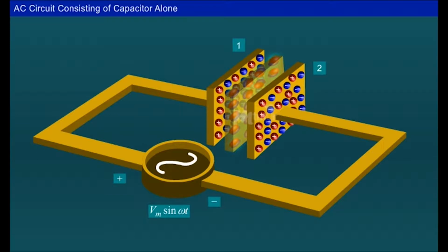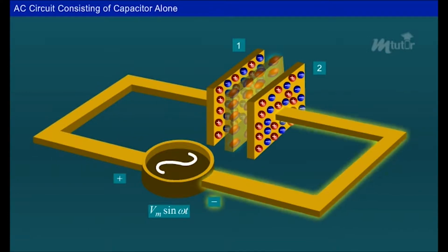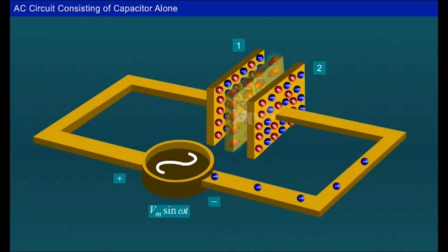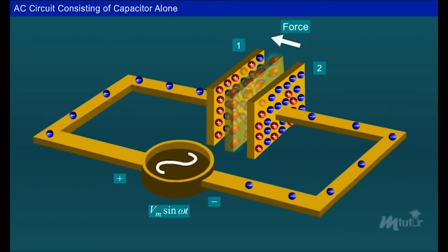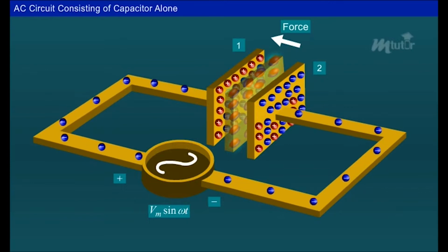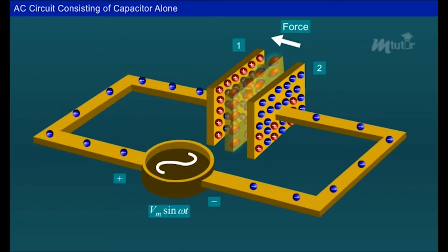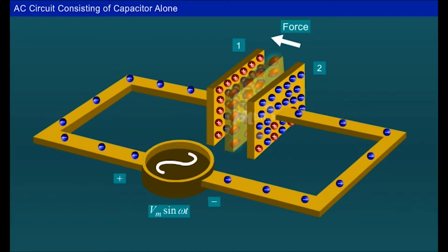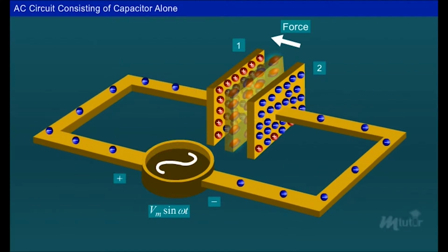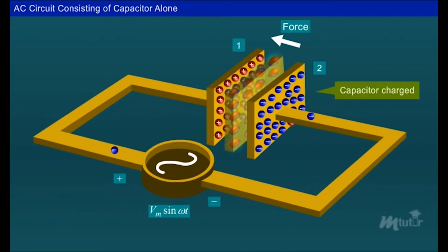Now, let's build an AC circuit with a capacitor instead. To keep things simple, we will assume the circuit contains a generator and a capacitor. What happens to the current once it has stabilized? Remember that in a DC circuit, as a capacitor charges up, it hinders the flow of current and the current slows down. Something similar happens here. As the generator's voltage increases, charge builds up on the capacitor and the current drops. When the generator is at maximum voltage, the current is 0.